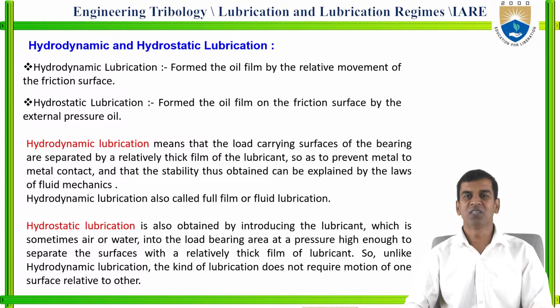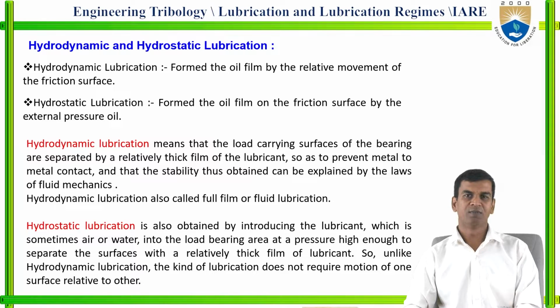In simple terms, lubrication is application of a substance between two metal surfaces in order to reduce friction, wear, and heat generation. In hydrodynamic lubrication, the oil film is formed by the relative motion of the two surfaces, whereas in hydrostatic lubrication, the oil film is formed by externally pressurized oil.